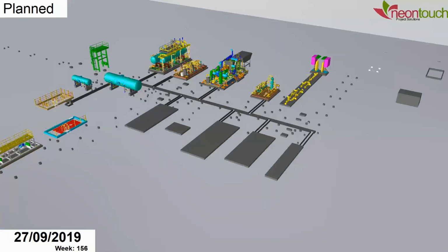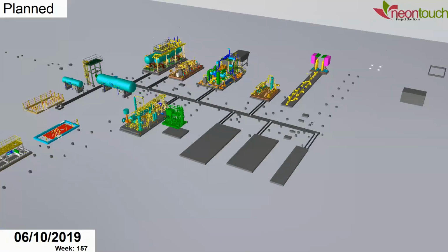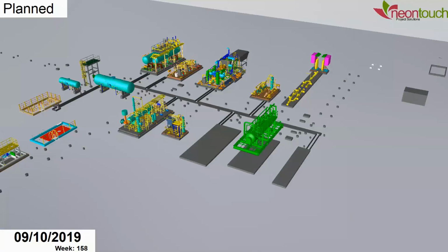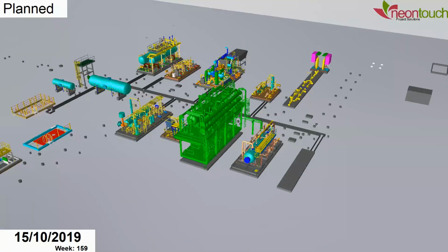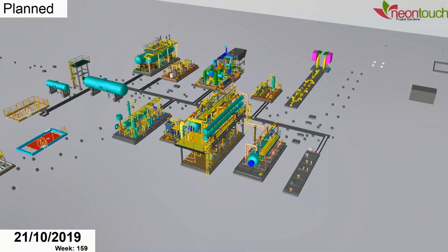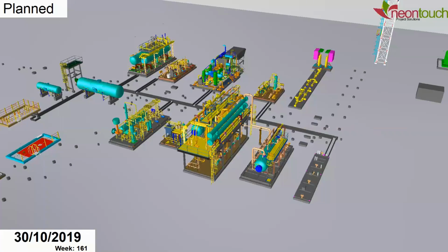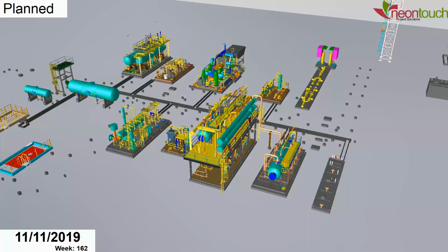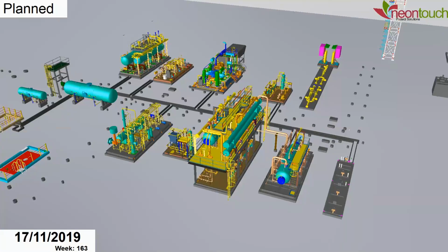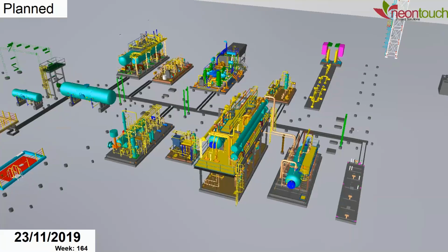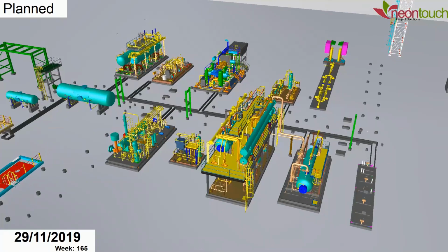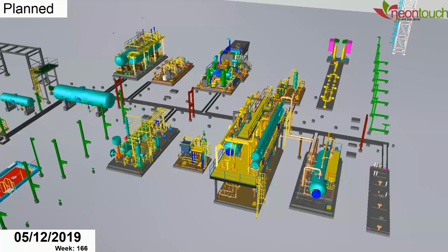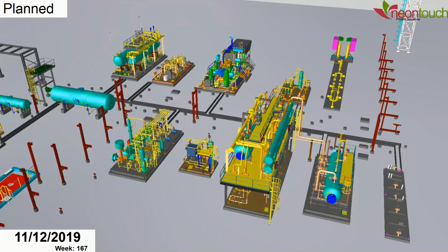Again, with a model like this, you can begin to look at optimization. You can begin to say, wow, should the equipment actually be in before I finish my pipe racks? Or if an equipment is delayed, what is the new sequence I'll use to make sure that things don't get blocked in and we have to cut things up to put equipment there. So you begin to look at some of those details almost in real life.